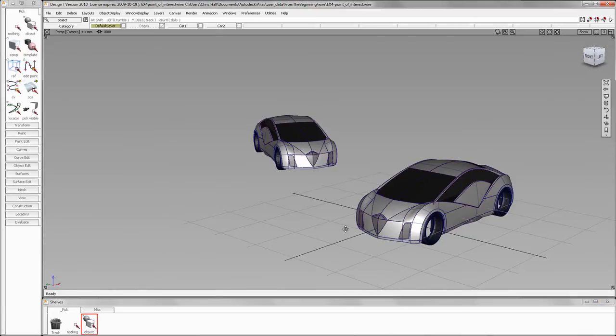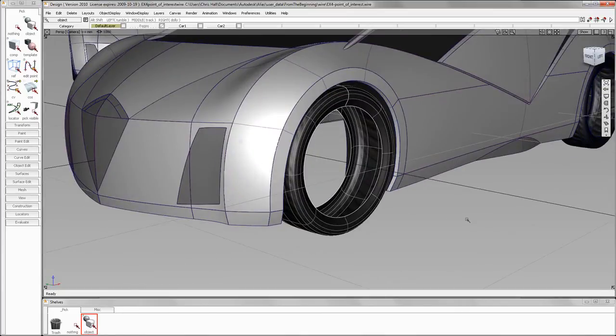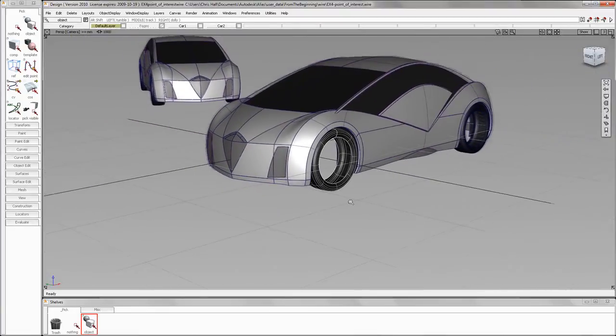Okay. One other thing about Look At, so we'll just do pick. Let's pick this object again. If I hold Shift and Alt key, see this top icon right here in our view bar? If I just pick that, that's going to zoom right up on that. Okay, so it's the same thing as using the View or the Alt-L hotkey.